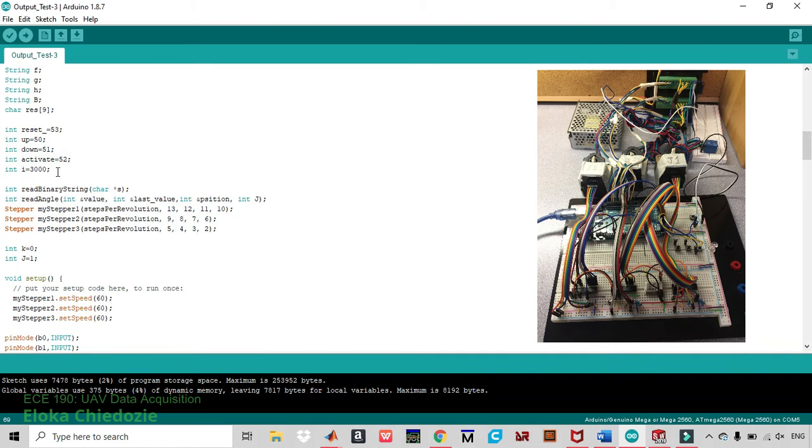So this I increment was a safety feature that was used to shut off power to the circuit. So whenever the circuit was inactive, this count would start immediately, and if the count finished before the next activity pulse, it would shut down all the motors and cut off power supply to the circuit.